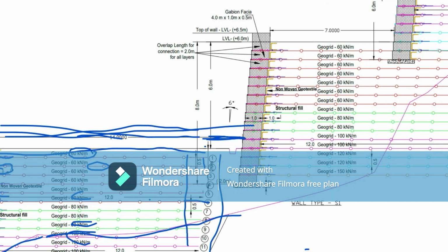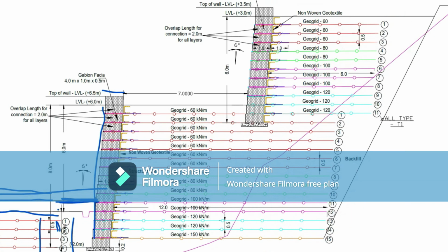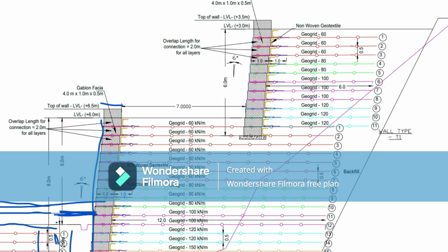Then again after 2 meters of unreinforced soil, the second one is constructed, with each layer 0.5 meter, again the same height of 6.5 meters with the same Gabion box design. After that they provided the third one along the ground level, 3.5 meters, with all Gabion boxes of the same dimension, and the geogrid length is 6 meters.